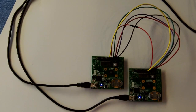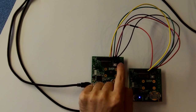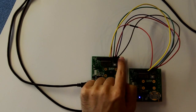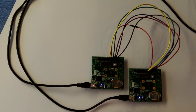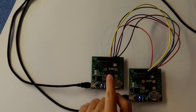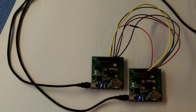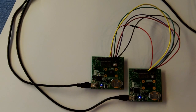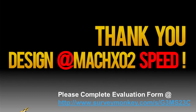Push 1. Once we push 1, the colon in the center is going to stop blinking to indicate we're in set mode. Push 2, we can change the hours. Push 3, and we can change the minutes. Once we're done, push 1. You'll notice that the slave board has now been configured with the time. Come back to the master, push button 4, and we can see the seconds that are being displayed on the clock. Push button 4 again, and you can see the clock running again. That's it for Usage Guide 56, and I'll hand it back to you, Dave.